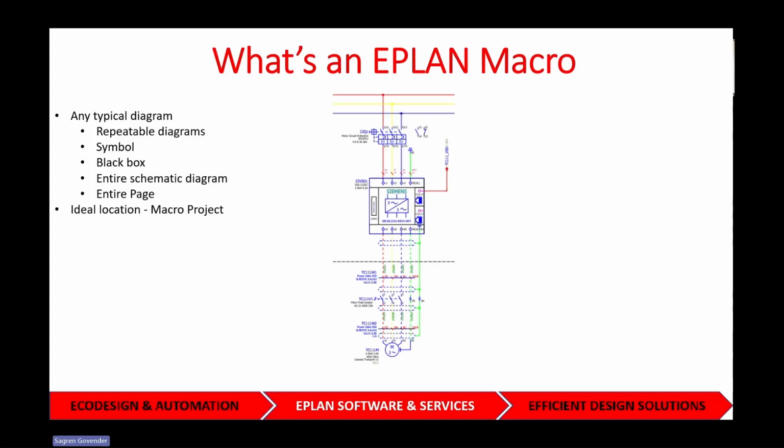So ideally, you want to place your macros in a macro project. And I'll talk about macro projects and the difference between that on the next slide, between the macro project and the schematic project, that is. But ideally, you want to create your macros in a macro project. And nothing stops you from copying a schematic project that you've already created and pasting it into a macro project and making it into a macro. So there's things that you can do to minimize the time that you spend creating these macros. And I'll touch on some of them a little bit later.